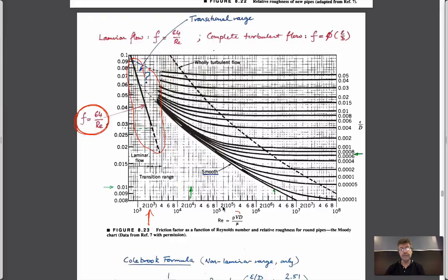And we see that as we get faster and faster velocities, then depending on the kind of pipe we have, if it's a very rough pipe, we get a transition to turbulent flow occurring quite early at a low Reynolds number. If we have quite a smooth pipe, we have a transition to turbulent flow occurring quite late. But from these, we should be able to define what this head loss is. And so we're going to calculate the head loss as a function of the length of pipe to its diameter, its friction factor, and how quickly fluid flows in it.